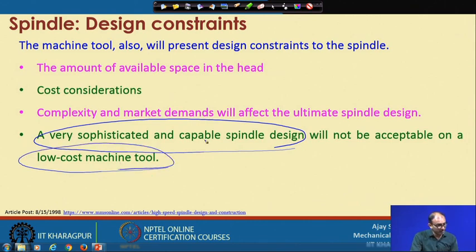First you have to find out whether your machine is capable in terms of stiffness, damping of vibration, and axis orthogonality, that means the x, y, z axes should be exactly perpendicular to each other, which we have seen in geometric errors. So, the machine also demands something from the spindle application. Better to first see the level of accuracy of the machine tool, and then decide which type of sophisticated spindle you can use for it.